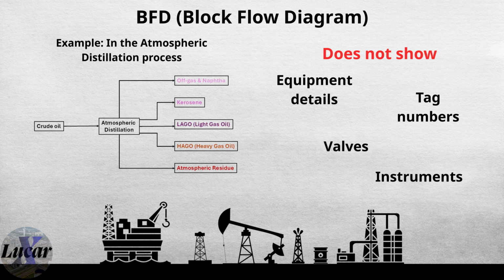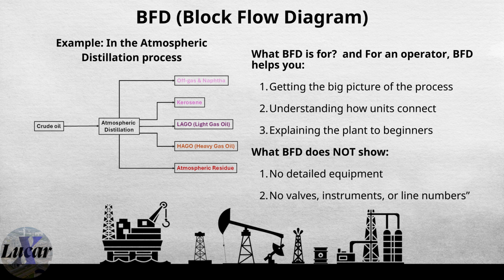To summarize the BFD, here are the key points to remember. What BFD is for: for an operator, BFD helps you get the big picture of the process, understanding how units connect, explaining the plant to beginners. What BFD does not show: no detailed equipment, no valves, instruments, or line numbers.